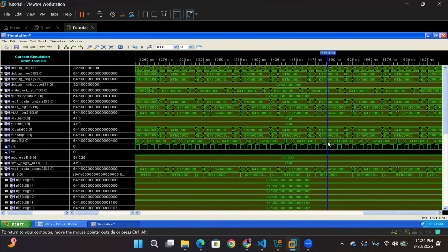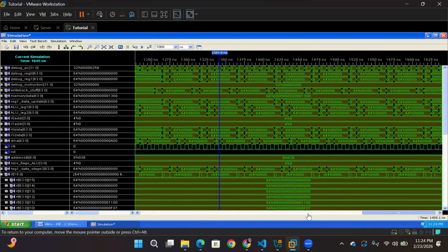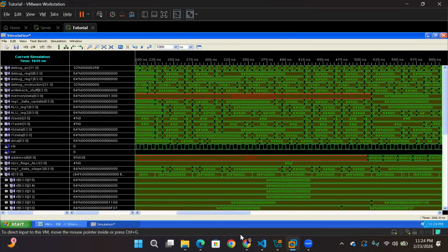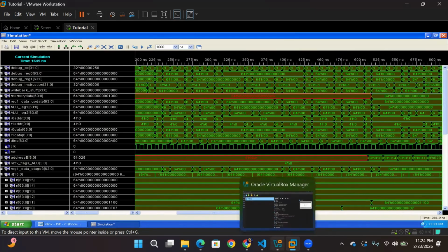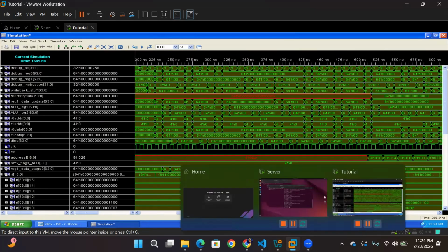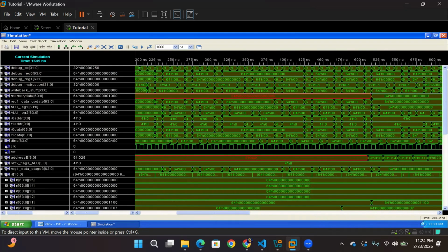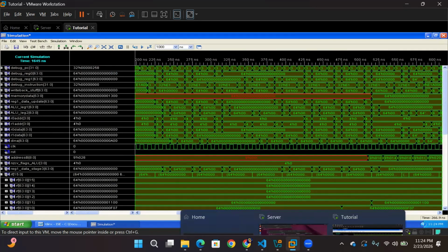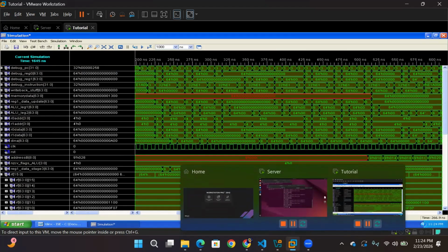So by summarizing this part, I think we have implemented most of the R-type, the I-type memory instructions, LDR, STR, and also conditional branch statements, because all the 16 conditions are being met. If it's a branch signal and the condition is taken, then BGE, BLT, and all the other 16 conditional branch statements are also supported logically.